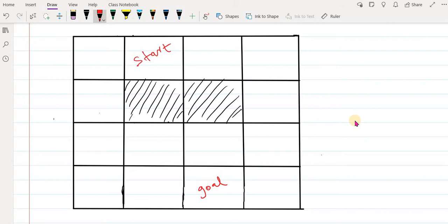So in the grid-based method, what we do is put a grid containing different cells, dividing the configuration space into different cells. These are horizontal and vertical lines, and by this method we divide our configuration space into small cells, as you can see, these small boxes.